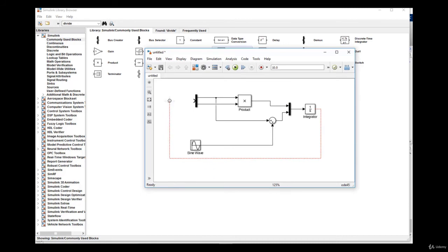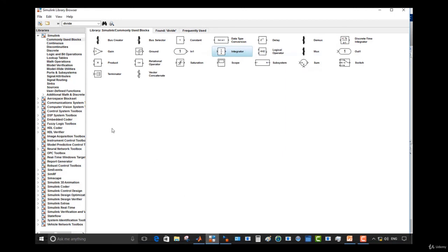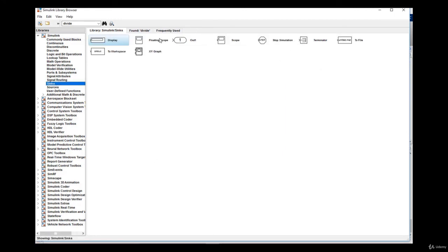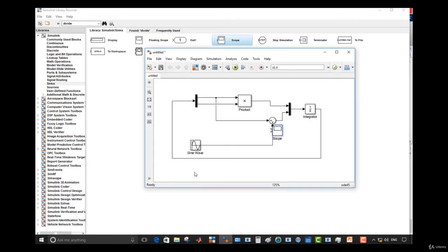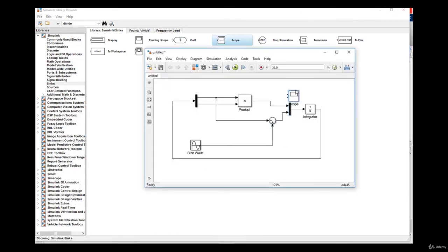Okay, here we create x2 dot, which equals x1 plus sinus or u, and create x1 dot here, which is equal to x1 times x2. We can use an integrator block and connect the mux output to the integrator input. Now we should use a scope in order to show the output. Here we can divide the scope into two separate parts.